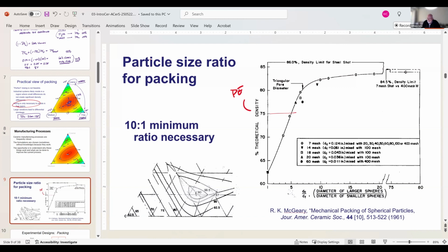What he did is he looked at the diameter of large spheres to small spheres, and recognized that his are all very narrowly distributed. When you look at the slope of this curve, and you come down here to 10, versus 100 out here, or 75, my difference is about 1.5%. But notice that here's my 7-to-1. This is trigonal packing. This is 7-to-1 here, roughly 6.5-to-1, 7-to-1.